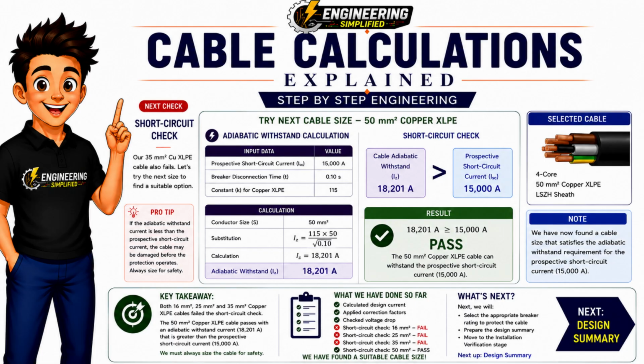At last, we have found a cable that passes every design check. Although we originally selected a much smaller cable based on current carrying capacity, the short circuit calculation proved that it wasn't suitable for this installation. This is exactly why every cable calculation must include a short circuit verification.